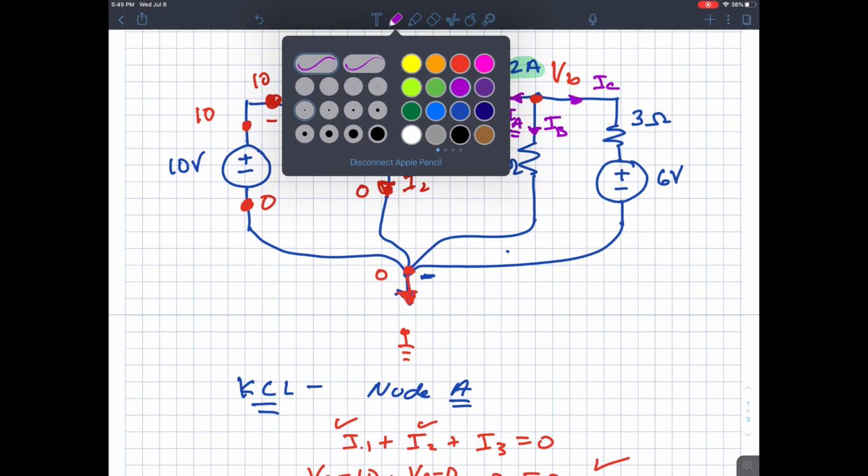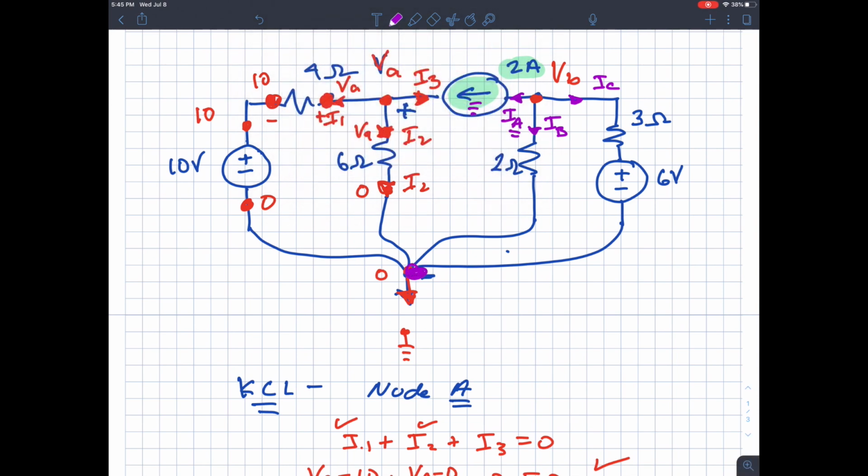So here's a dot. I can make it a great big dot that I can slide at the reference node. I grab the dot, I slide it and I put it on one side of the 2 ohm resistor. And what is its value? Well, it started out at 0 volts. It's still 0 volts as we slide along a flat spot on the mountain. This is 0 volts.